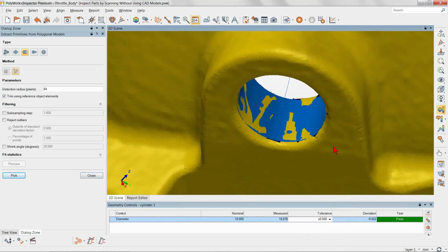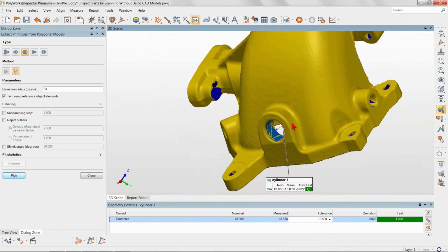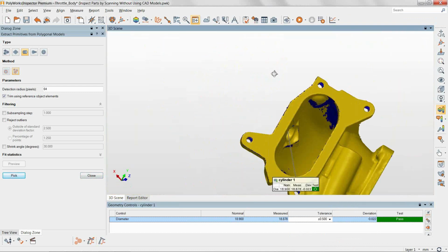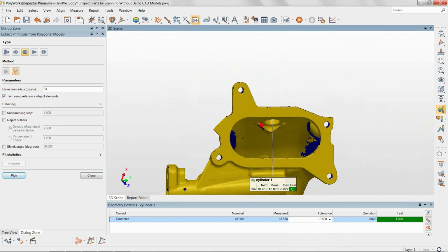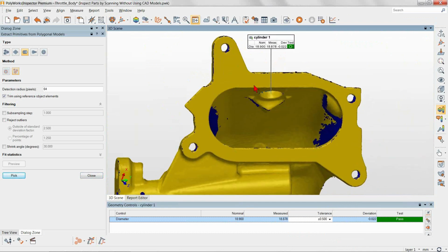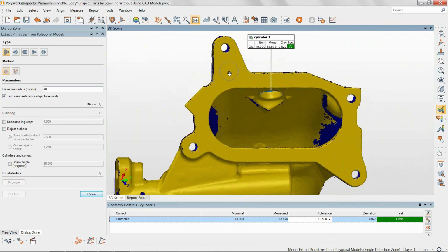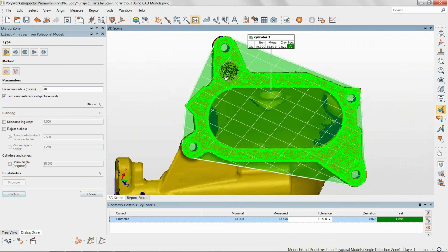And let's go ahead and finish the print inspection on the front mating plate here that holds our 4 bolt holes. The first thing that we're asked to check is the flatness of this surface here. So let's go ahead and just switch everything back to default, as I'm fairly confident we can grab this plane quite easily, and we do so.